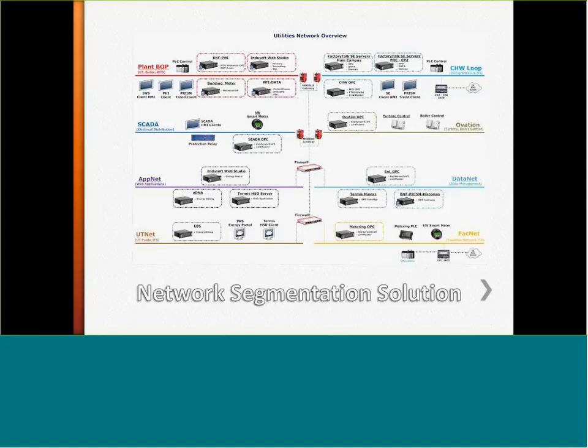One of the challenges was to be able to have different control platforms coming into this energy dashboard, energy portal. The platforms that we had in the past, we ended up modifying them so that we can bring data across the networks in a secure manner. So we segmented our networks and created 2 more segments: the application network, which is the InduSoft, where the InduSoft Studio resides, and then the data network. We have the 4 networks up on top of this graphic.